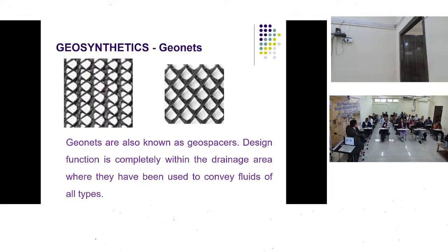In the lower sides, I can have some channels installed where the water gets collected. Those channels can be led to a sump, and that water can be pumped. This is one of the applications in which even in very deep basements, 2, 3 or 4 level basements, geonets have been put on the outer sides of the walls, so the basements are under much drier conditions.